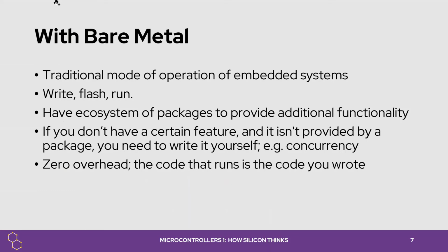Yeah, thank you, Miko. Using a microcontroller with bare metal is the conventional way to write the code for an embedded system. The process starts with writing the code, continues with compiling the code for the microcontroller currently in use, and then uploading it to the platform. If you're using a development board, generally you upload it using USB. Finally, it ends with running and debugging the implemented program.